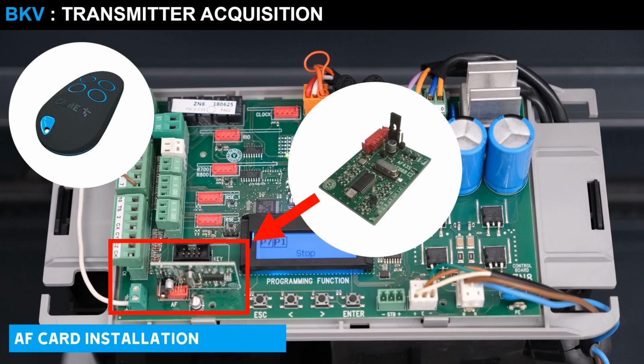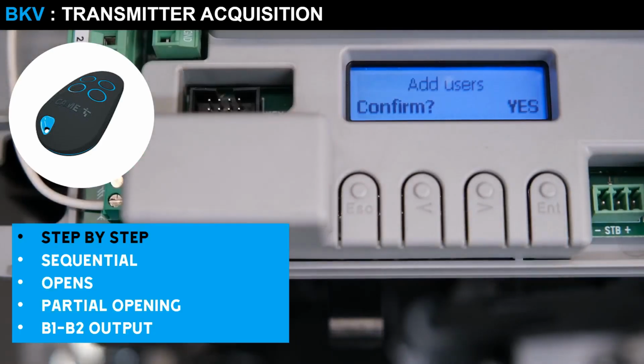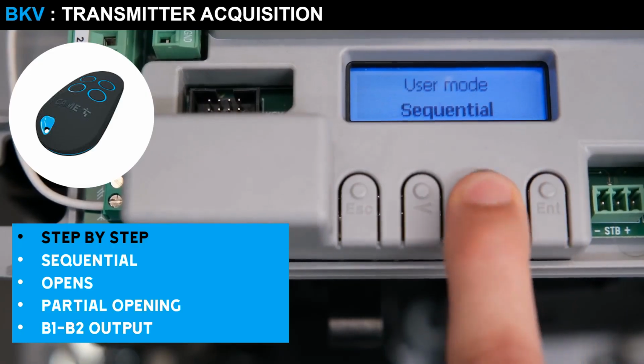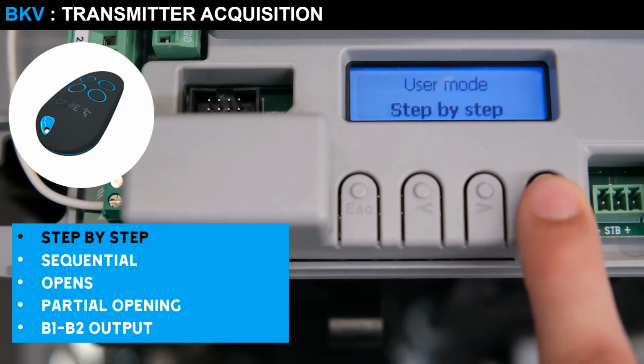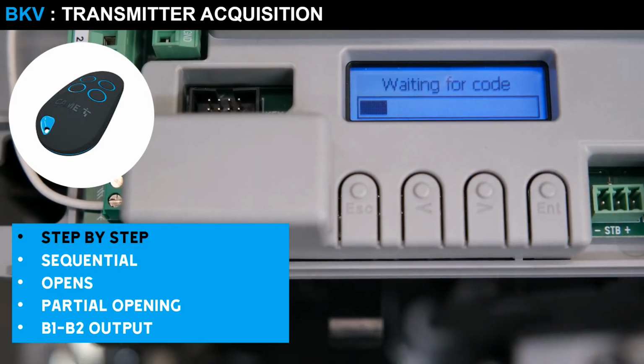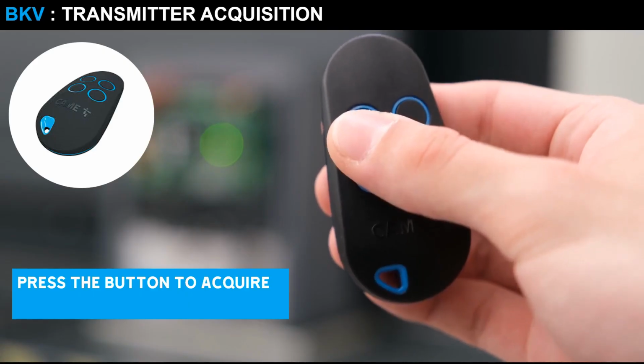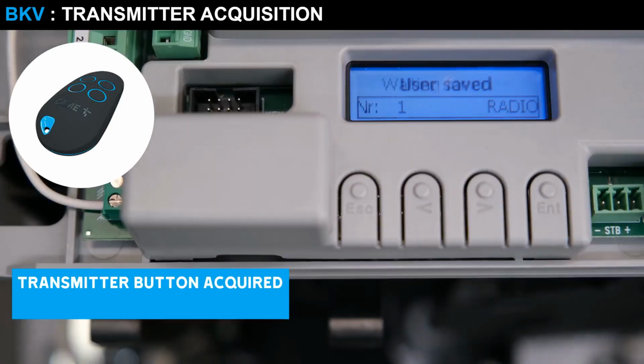To program a transmitter, the AF board must be installed inside the control panel. First select the function to be associated with the transmitter button, and confirm with Enter to proceed with the acquisition of the button. Press the button to acquire. The display confirms the memorization and the user number associated with that button. The procedure will wait for the acquisition of a new transmitter. If no new button to memorize is received, the procedure will move on to the next step.